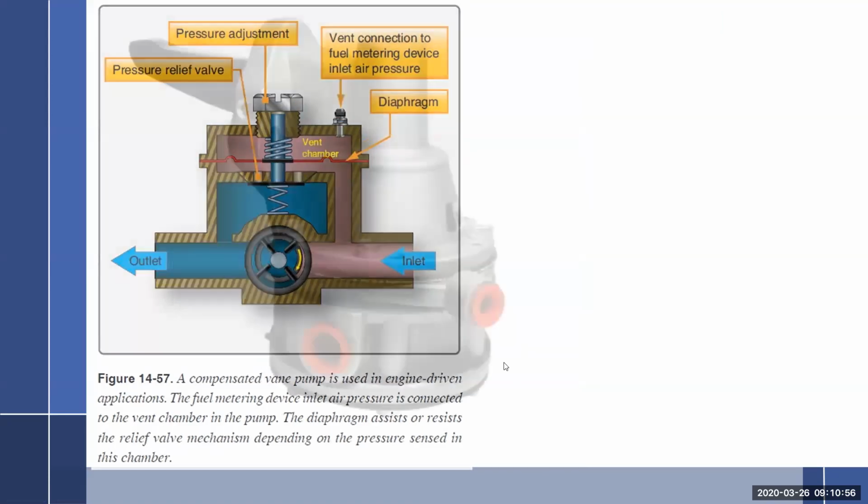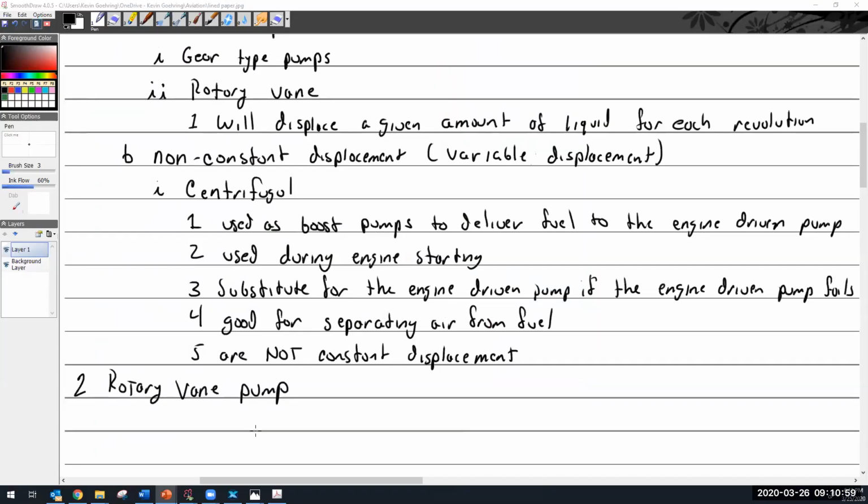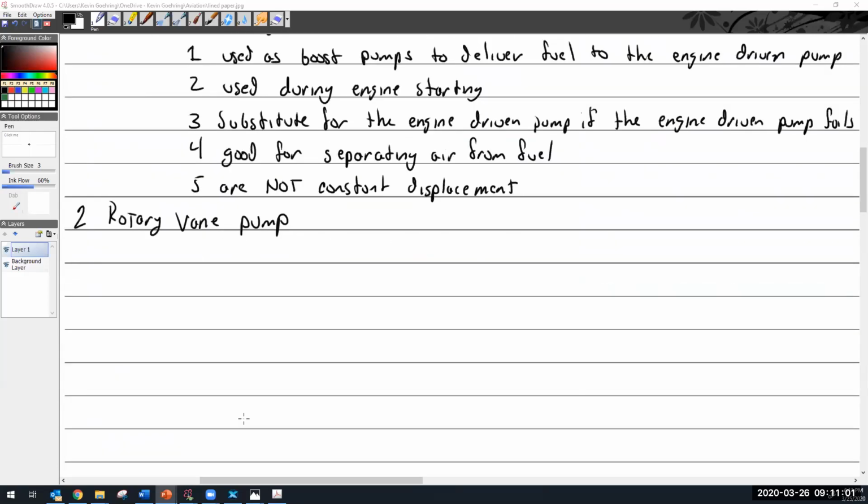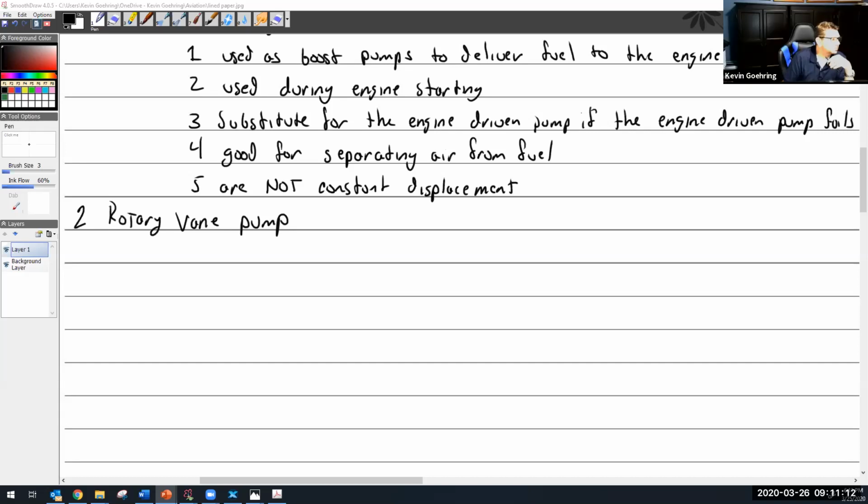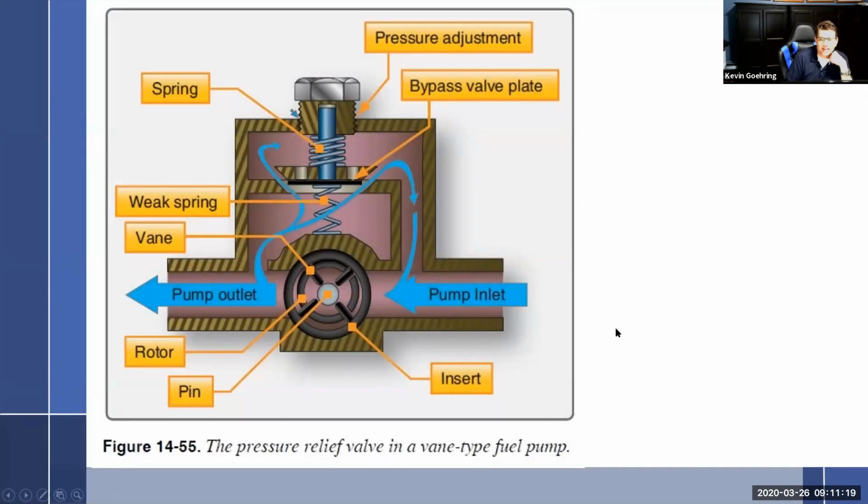Hey, Kevin, kind of a question for you. When you said it recycles through the pump on back there, if you were to hook up a tank to it and then have an electric motor, would it recycle back out the inlet, or would it just cycle through the pump? Would it through the pump. Okay, no, it wouldn't push it back. Well, let me bring up the slide. It's exactly how it's drawn. They drew it 100% accurate. If it can't get out this way, or it's not using it, it comes up through here, back around to the inlet side of the pump.